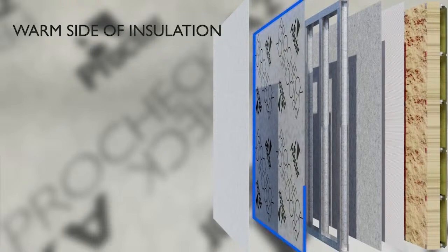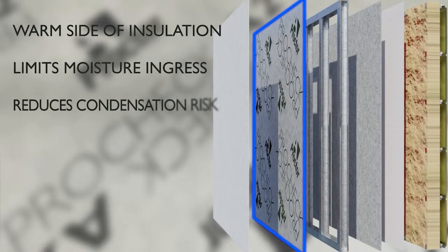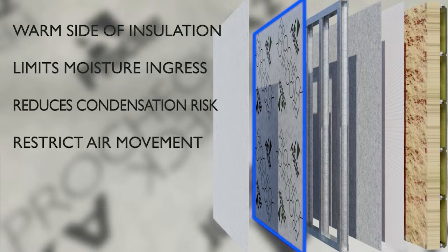In the UK, the climate dictates that vapour typically moves outwards from the warmer interior to the colder environment outside, so this type of membrane is placed on the warm side of the insulation. In this position, it prevents the vapour moving to colder areas where it can condense into liquid water. The A in AVCL refers to the ability to inhibit the movement of air, but whilst all vapour control layers will restrict air movement, not all airtight layers restrict vapour movement. Sometimes it's advantageous to use a membrane which is airtight yet vapour permeable, and we'll discuss this, along with envelope airtightness, shortly.